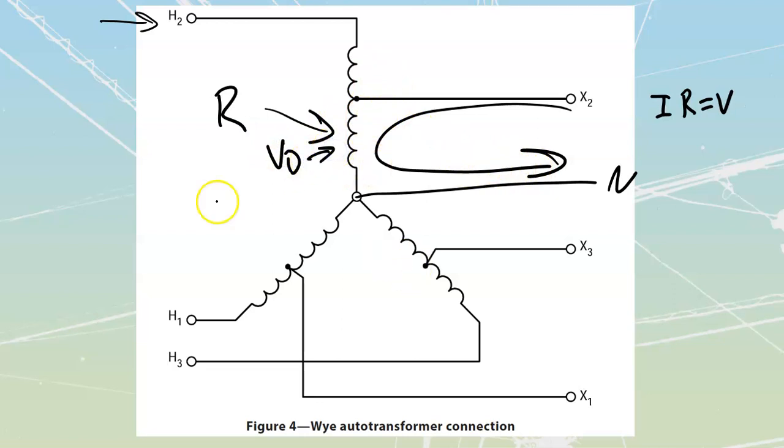And as a result, all of a sudden, all of my phasors are going to go weird, because I'm going to have 2 lines that have larger phase voltages, and then one where the phase voltage is going to be smaller, because I have dropped that value of voltage through the fact that I've got a large amount of single phase current. And this is now going to lead to a pile of different problems.